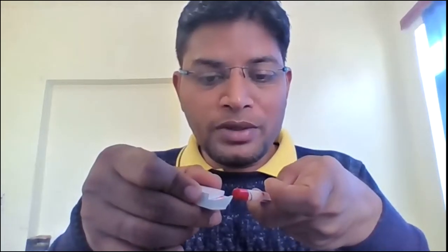If you give some depth of cut, then the area remaining over the single point cutting tool is very small. So we have to make sure that whatever chip falls over this rake face is immediately removed from this surface area. If it stays for some time, it will stick to the tool face, and that will create defects, and because of that the tool will weaken. So the chip should be removed easily.